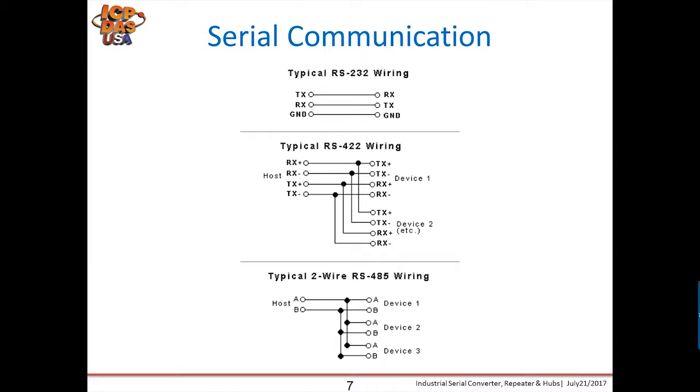The next one will be the RS422. As I said, it's used on Apple computers. It provides mechanism for transmitting data up to 10 megabits per second. RS422 sends each signal using two wires to increase the maximum baud rate and cable length. RS422 is also specified for multi-drop application, where only one transmitter is connected to and transmit on.